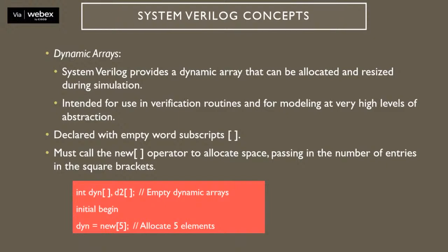Now we have discussed till here, they were all with respect to fixed arrays. Now, what we are going to see, the unique feature in SystemVerilog, is the dynamicity in dynamic operations. The dynamicity is introduced in 3 ways here. First one is dynamic arrays. In a dynamic array, usually when you go for fixed size, the size is set during the compile time itself.